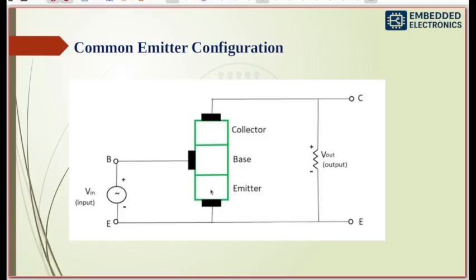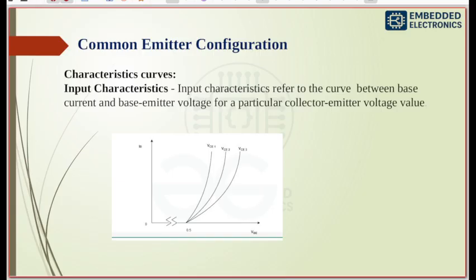The emitter current is the sum of the base current and the collector current. A CE design offers a modest current gain together with a strong voltage gain, so it is frequently employed in voltage amplification. In phase relationship, it flips the phase of the input signal in relation to the output. It is typically used in general purpose amplification, such as audio amplifiers and RF amplifiers.